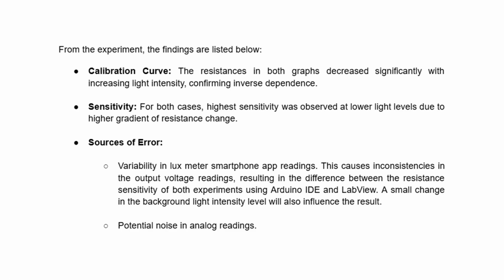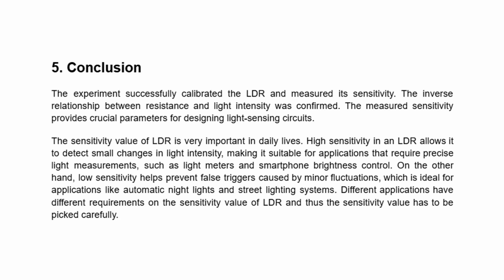For the last part, which is the sources of error: variability in lux meter smartphone app readings. This causes inconsistencies in the output voltage readings, resulting in a difference between the resistance sensitivity of both experiments using Arduino IDE and LabVIEW. A small change in the background light intensity level will also influence the result. The next source of error is potential noise in analog readings, which also influences the final result of our experiment.